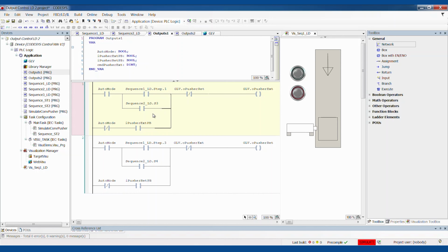Second thing we really want is maintainable. Well, what does that mean? Obviously, readable is part of that, but it also needs to be changeable, which is what I just talked through, is going back and changing that sequence or which step of the sequence is driving the output. And we want to be able to come back and follow cause and effect in the program for debug purposes. Now, this right now can do that. I can cross-reference this back to whatever sequence it came from.